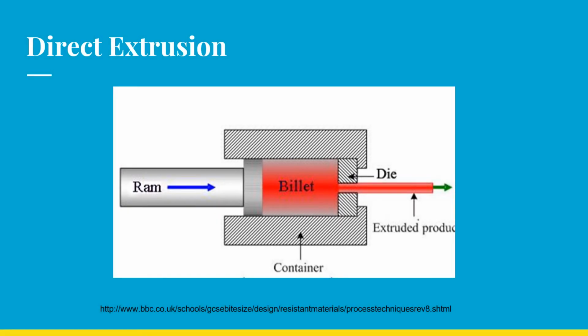In direct extrusion, a solid ram drives material through the die to make the desired shape. The extruded product that comes out of the die always has a constant cross-section. Direct extrusions must have lubricant to reduce frictional forces. By reducing frictional forces, lubricants also reduce temperature and prevent the extruder from overheating and having defects.